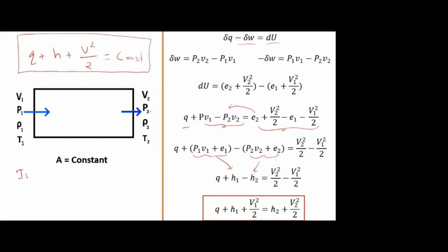But if you take isentropic or adiabatic, the condition is T0 is equal to constant. That is, there is no heat addition or rejection. In that case, this Q will be 0. You will get only H plus V square by 2 is equal to constant for isentropic and adiabatic. So mostly we will use this equation. Only in the Rayleigh flow, we will take this Q where we are dealing with the heat transfer. So the general equation is H plus V square by 2.